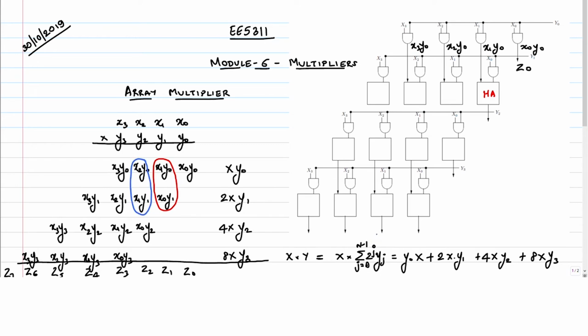So that will also be a half adder, right? So everything here will be a half adder. Okay. So you add these two numbers, X1 Y0, X0 Y1, you get a carry, right? That carry is now going to propagate from this red to this blue block. Correct? Because I need to add it to my next set of terms. Correct? So what will be the carry out direction?